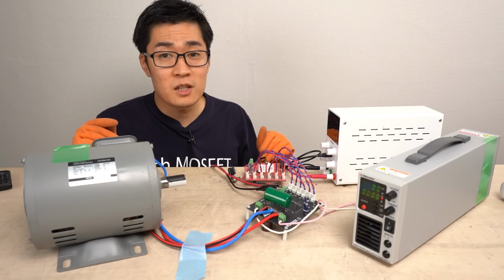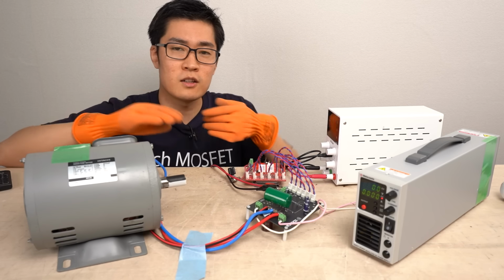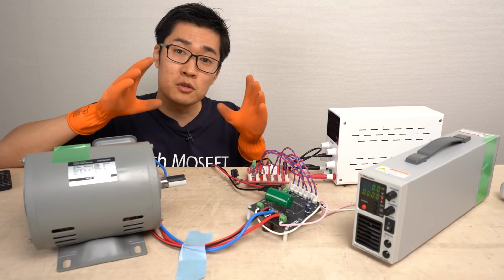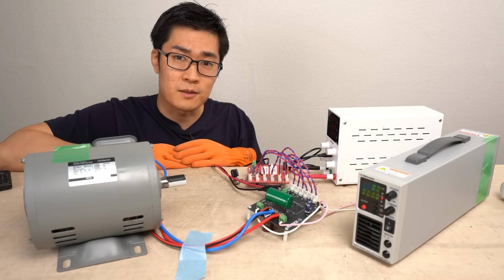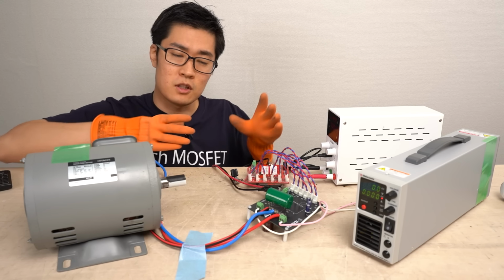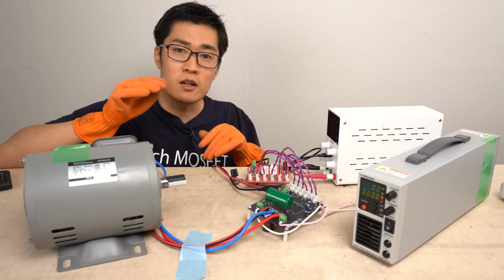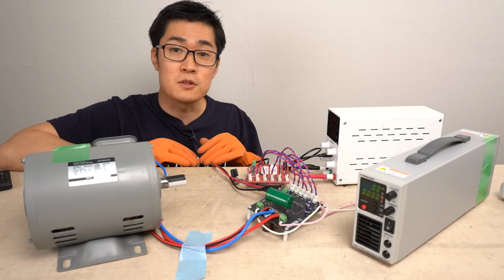When I was controlling the do re mi fa inverter, the motor made a tulululu sound during acceleration. But modern trains no longer make such distinctive sounds when accelerating or decelerating. The reason for this is that the inverter is controlled to reduce noise. Specifically, this is done by increasing the switching frequency from several kilohertz to over 10 kilohertz.